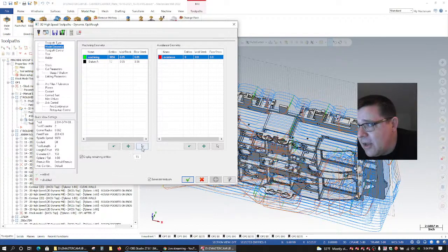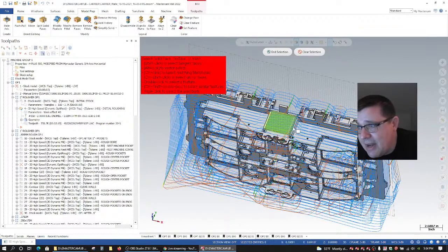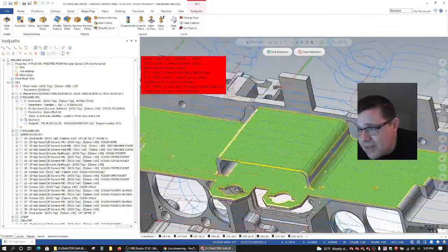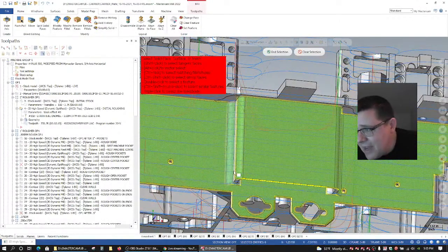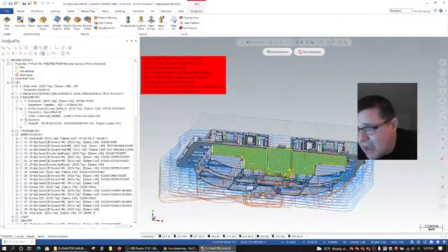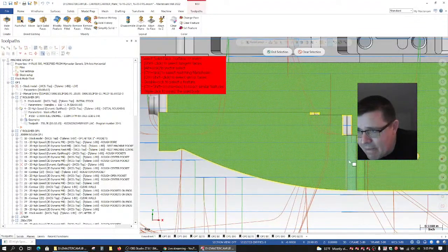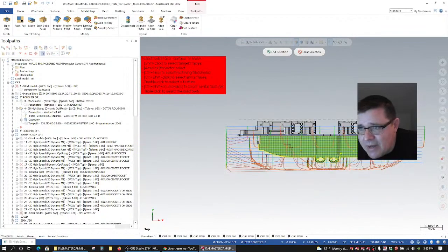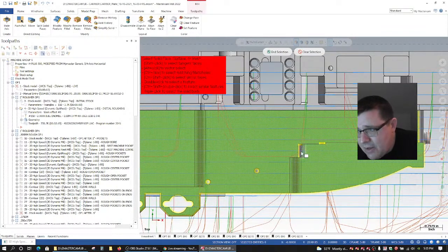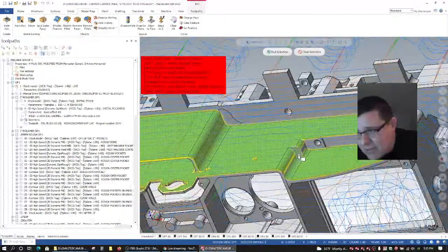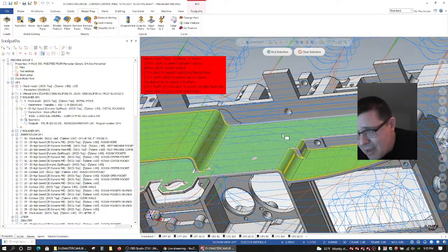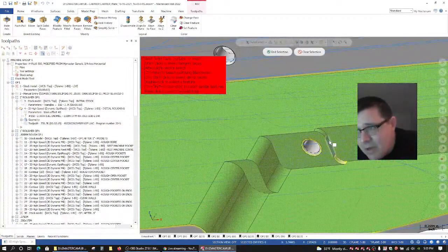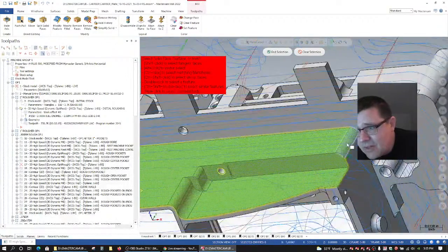So be careful when you go to pick a toolpath and you're going to the model geometry here. If I'm creating a toolpath from the top side, I may only want to select just the faces I can see, right? So if I look at this from the top view, okay, I know I'm not going to jump into these little holes, right? My tool is bigger than that, so I don't care. So really, I don't even need to worry about selecting these little guys here, because this top surface is going to get me there. It's not going to hurt anything if I do, so I might as well include all these little guys here.